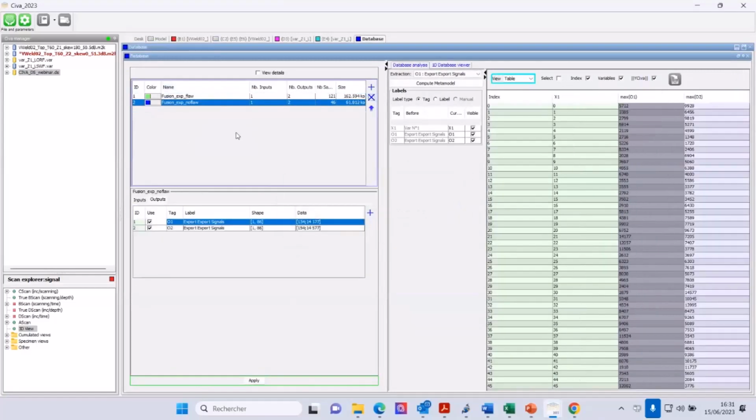So the idea is that after that, I will repeat the same logic with my simulation, with my variation files. Before loading and making the fusion of my variation files, there is also one important thing, for CIVA users that use CIVA UT in both simulation and experimental data. You know that calibration is important.